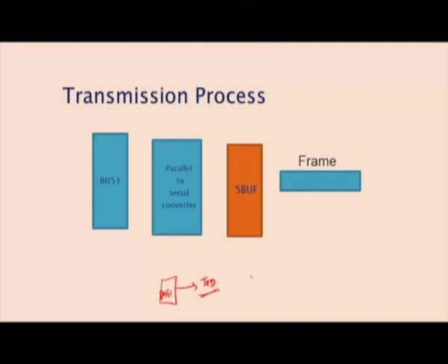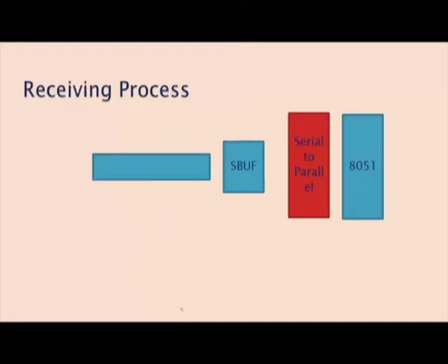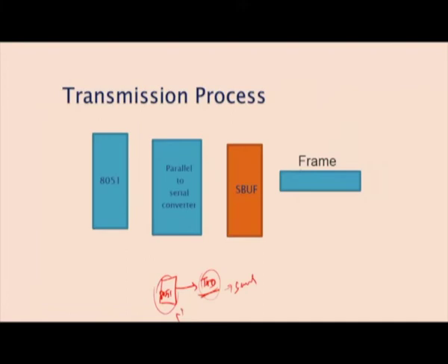So, within that, how is the data transmitted, or what processing is involved? The transmitter performs as serial data, okay, but the processor is a parallel one. So, how will the parallel data be moved to the serial one? Suppose you have data in port 1 that you want to transmit. The port 1 data, which is parallel data, will be moved to the parallel to serial converter. The converter converts D0 to D7 into serial D0 to D7. So, this is serial data.